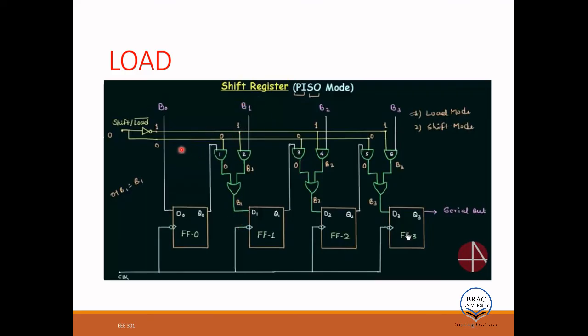So if you keep doing this, you'll see that initially it was 0, and for the other four it will be 1 1 1 1, something like that. So 4 1s, one more state is not showing here. You can show it here if you like, or you can just draw the timing diagram directly. Again here 0 0, then 1 1 1 1. For the output here it will be 0 0 0, then 1 1 1 1. Here will be 4 0s, 4 1s. So that's what is happening here, right? So this is the Johnson counter.